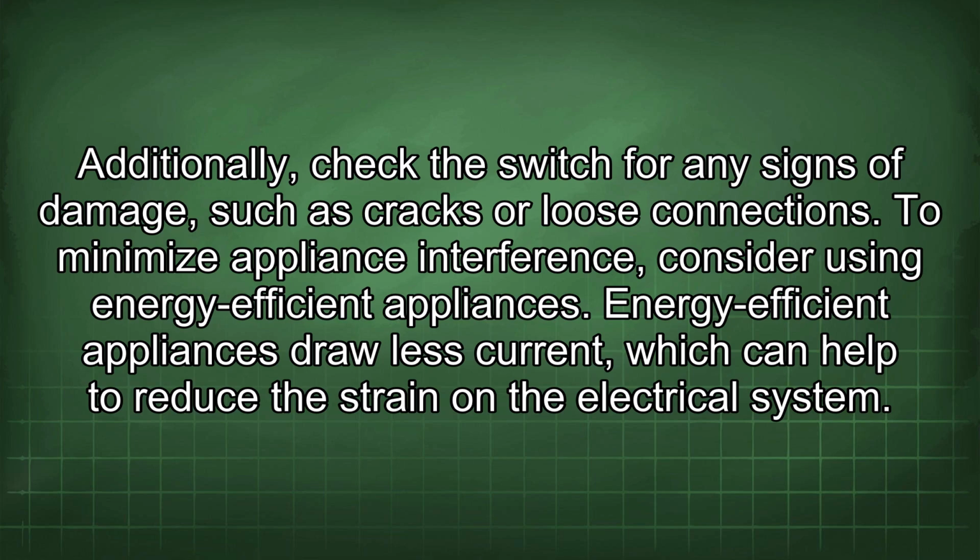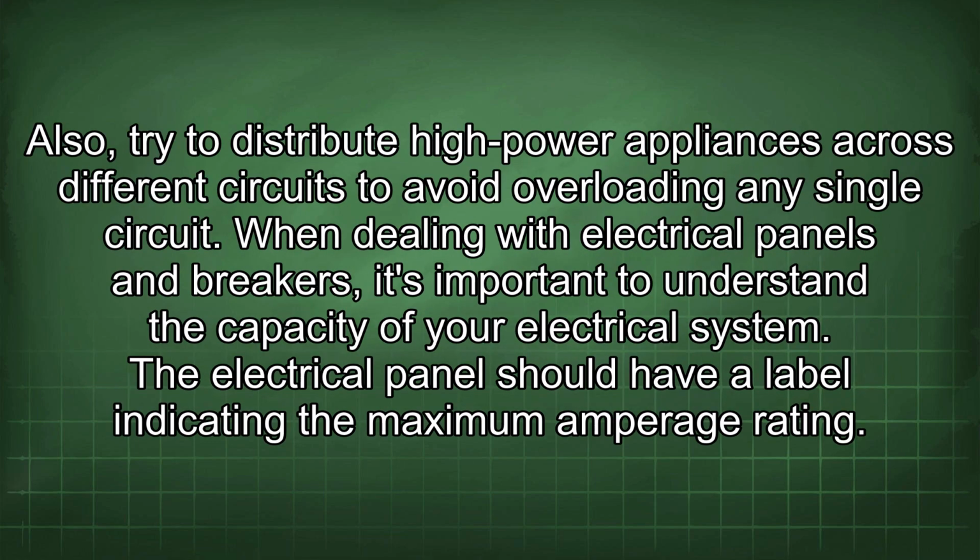To minimize appliance interference, consider using energy-efficient appliances. Energy-efficient appliances draw less current, which can help to reduce the strain on the electrical system. Also, try to distribute high-power appliances across different circuits to avoid overloading any single circuit.